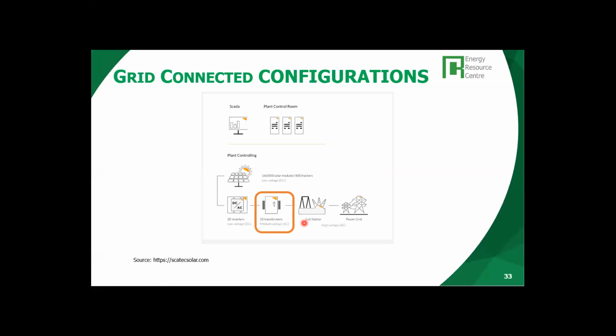Exactly. A little problem in all PV plants is the requirement of another internal transformer to feed the auxiliary service, to reduce or elevate, depending, from 0.55 kilovolts, the output of the inverters, to 0.4 or 0.22, I'm sorry, 220 volts, to feed the auxiliary service. So you need another transformer for the auxiliary service.